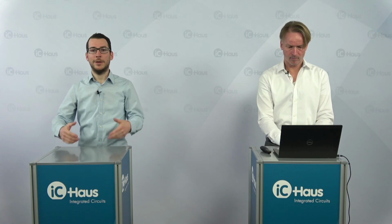Excellent, thank you. Next question: BiSS 2-wire requires some specific line pair impedance, i.e. 120 ohm, is the question. Okay. Well, that of course also depends on the transmission line. The 120 ohm are typical for setups like this, and therefore we have also considered it in BiSS Line. So you can find on our evaluation board also the 120 ohm termination resistance at both sides of the BiSS Line.